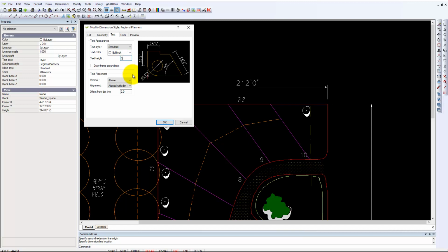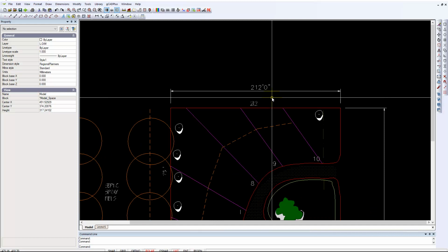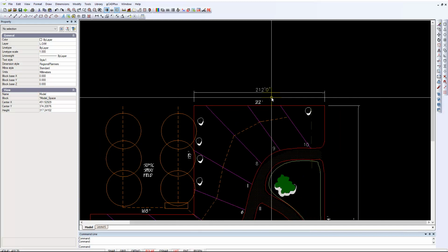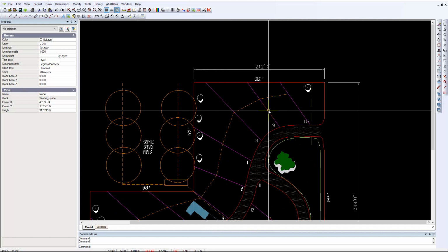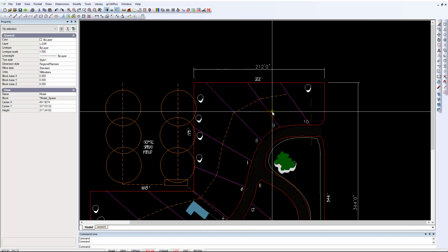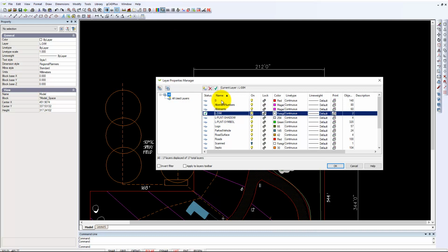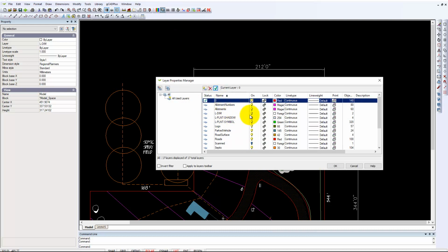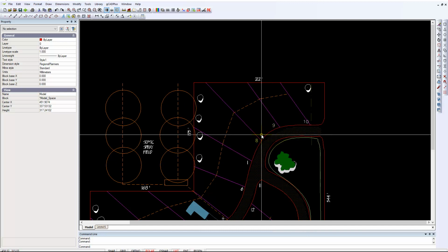Let's bring it down to 5, or just drop that a little, as you saw. So I'm happy now that we are checking our design, taking the dimensions directly from the model, and because we were putting all the dimensions onto a layer, we can easily put layer 0 on and turn the dimension layer off. So I like to do that sort of check. It certainly improves things.